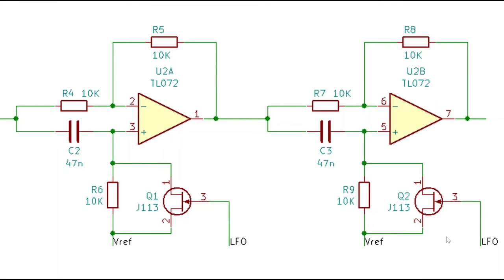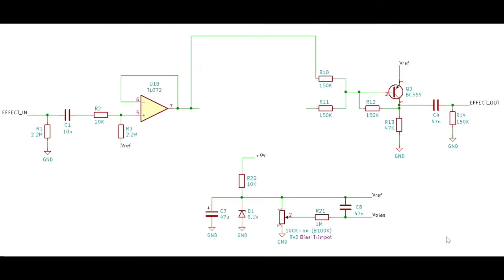You don't get V bias really at 0, even though you have it here. There is a voltage drop here, so this V bias can never be 0. There is a voltage drop, or there's some current flowing here, so that V bias is more likely going to be about 1 to 2 volts.